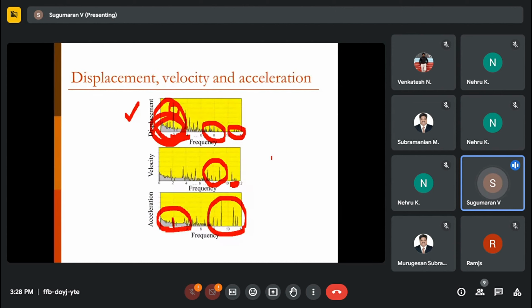Suppose I come home, mother is using a wet grinder for making idli maavu. Okay, so roughly 1200 RPM, maybe slightly less, because there is a belt drive that reduces the speed. Let's say about 400, 500 RPM. The grinder is rotating. For those kinds of medium speed applications, if I use velocity, this response is good for medium frequency range. So I will go for velocity.